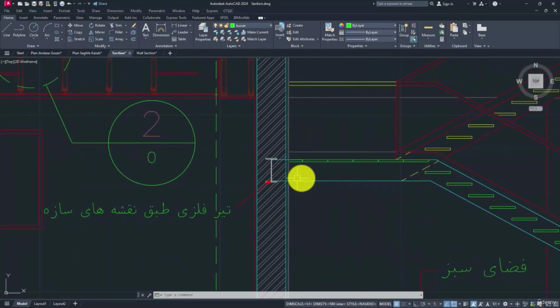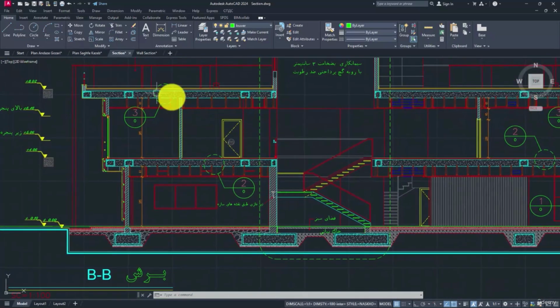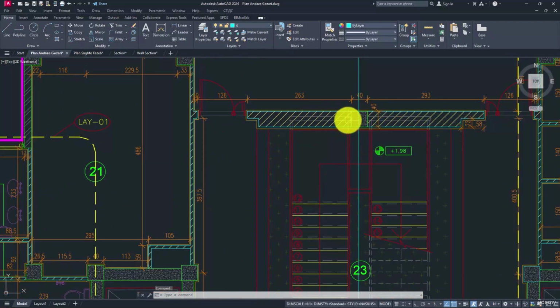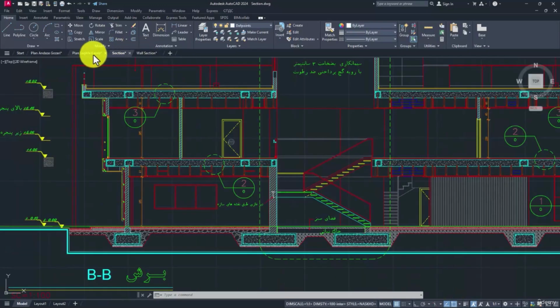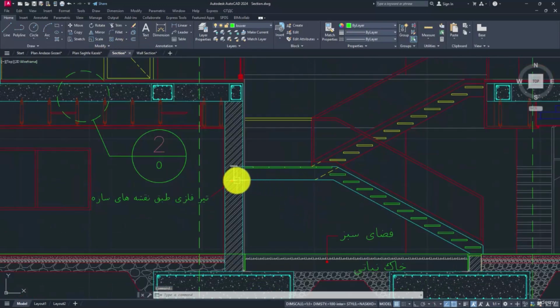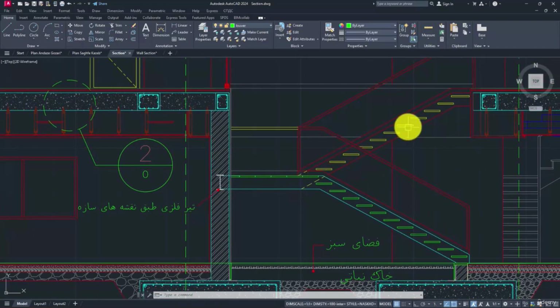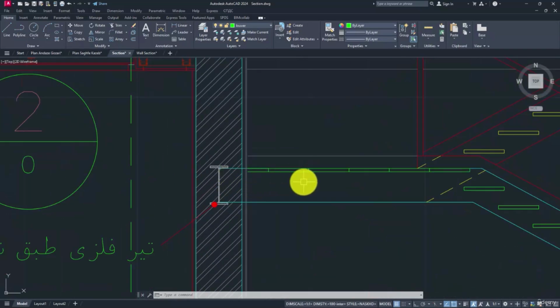As you can see, we have to check the structural plan that it has been welded to two other structural framings, and we got another profile at this part at the center, or at the middle. And as you can see, the stair is welded or connected or joined to the IPE or structural framing, and these are the supports, and this is welded to the IPE element.